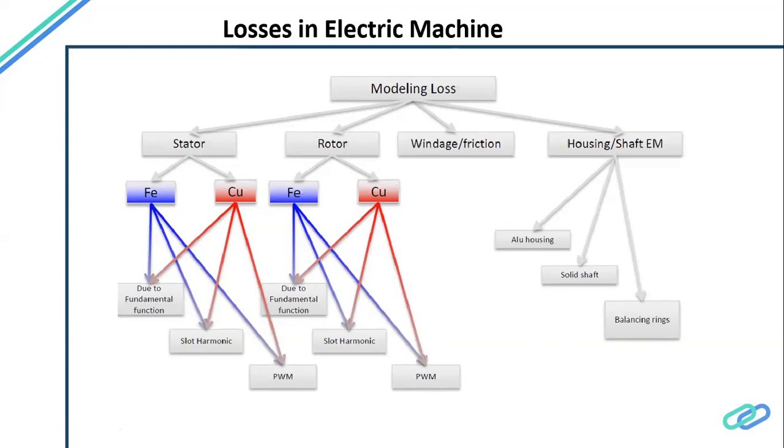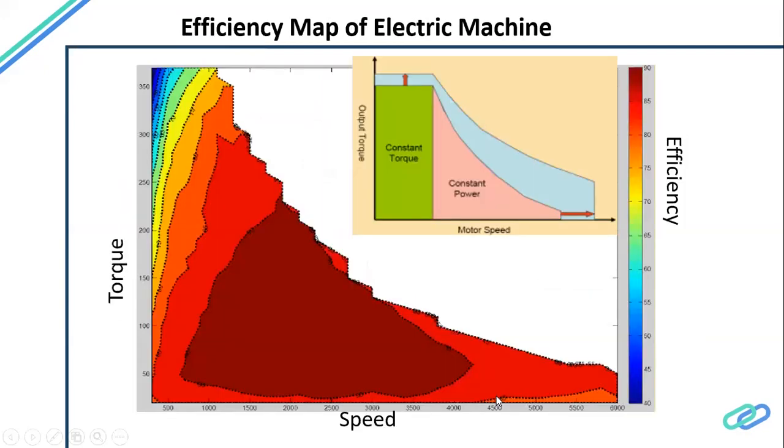We have to be very careful what kind of other harmonics are getting injected into the machine, because those are either producing negative torque, or producing I squared R loss, or increasing iron losses, because iron losses are very much driven by the frequencies that we have. So higher harmonics mean higher frequencies, and those losses will be impacted. So harmonics are at center stage when we talk about it.